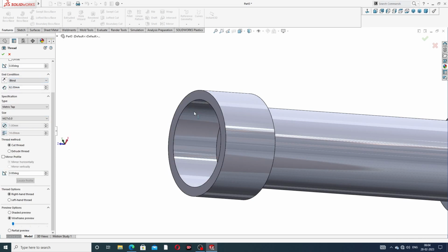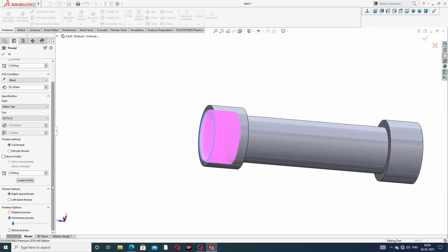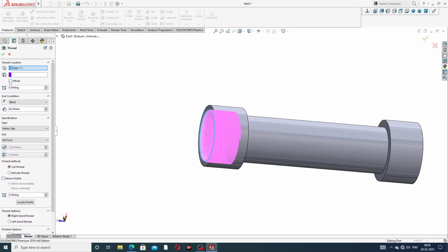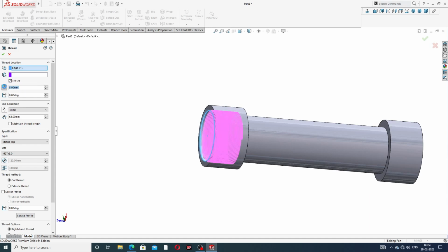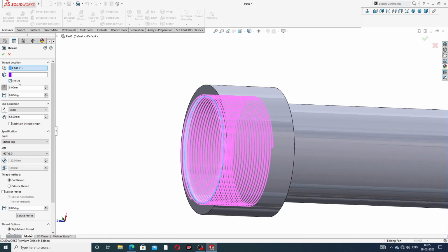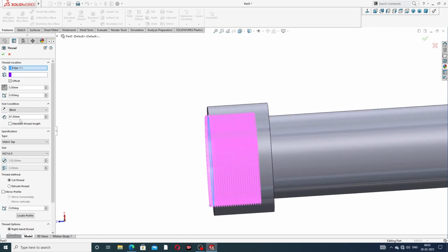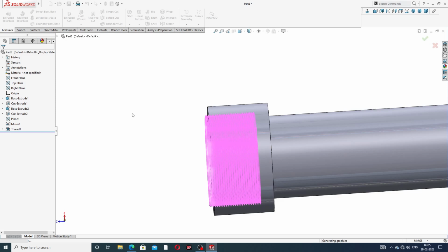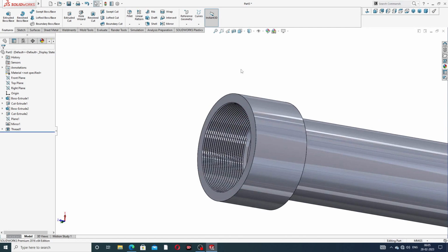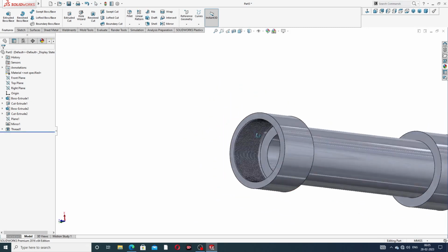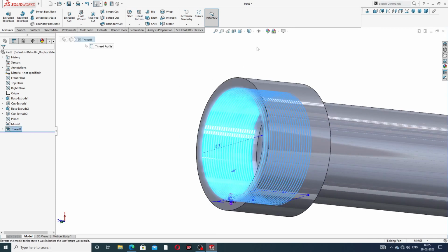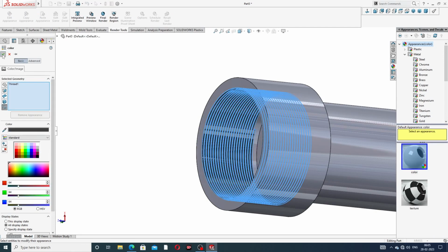Okay, and select this. Okay, and all points are correct, and click offset. Offset is 5 millimeter, and direction is upward. Okay, and this length is 62 plus 5, okay, 67. This is perfect, because 5 millimeter is upward, then 5 millimeter is added here. Okay, all is perfect. Metric tap. Okay, this is perfect looking and correct, and this thread is used, and some black color is looking very nice.